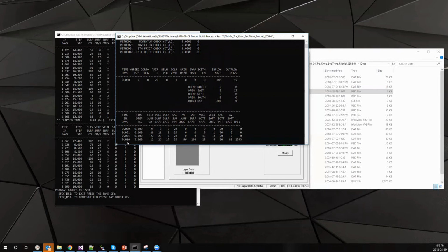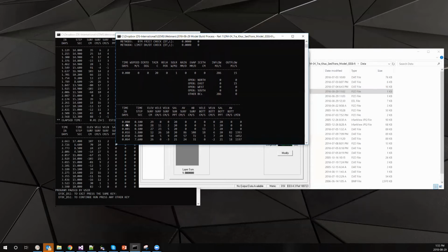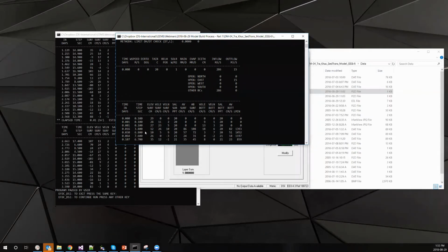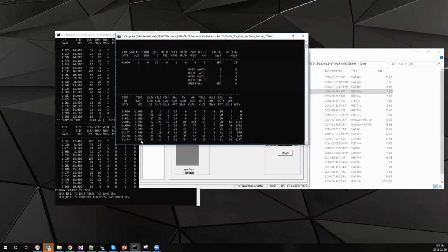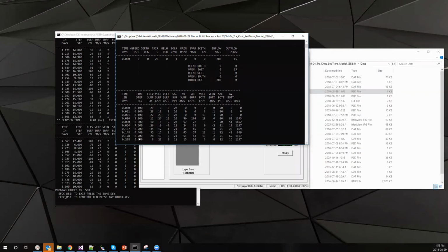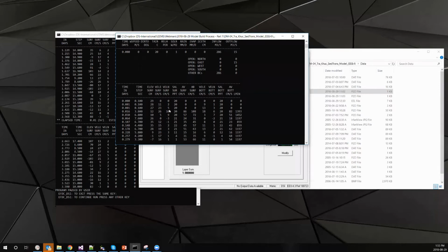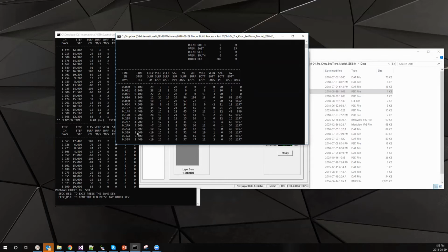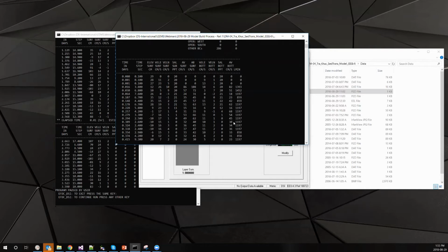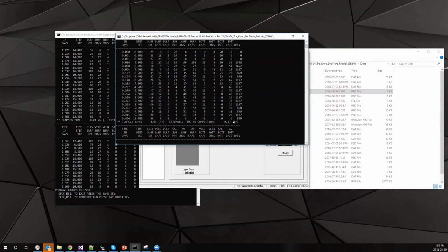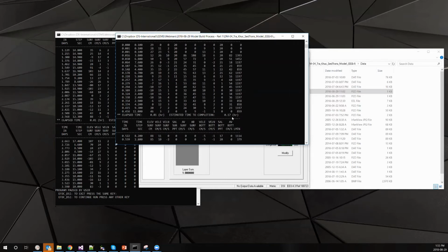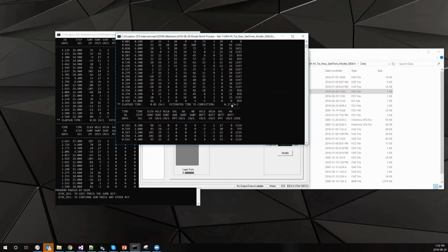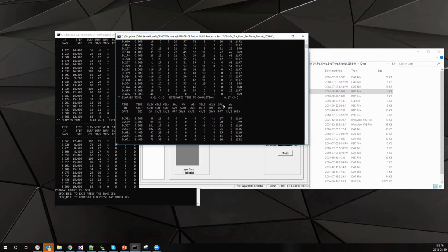You'll notice that it starts off at a relatively small time step here, and then rapidly begins to move faster and faster as it gets further into the run. Because we have density turned on now, and we have a multi-layer model, you'll notice delta T is smaller. It takes a little bit longer to run, but I'll let it wrap up. For this 10-day simulation, with 2,000 cells and 5 layers, it's going to take roughly 10 to 12 minutes.